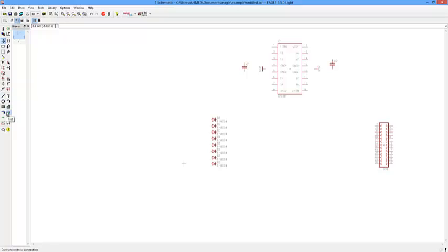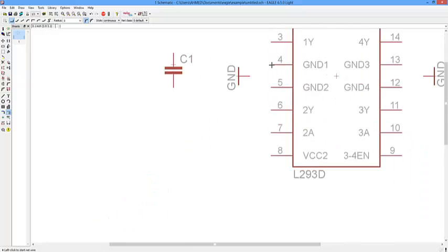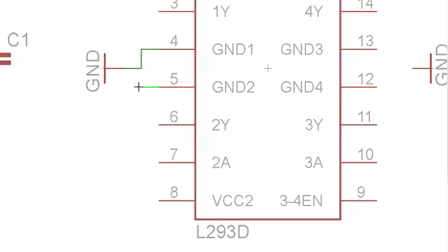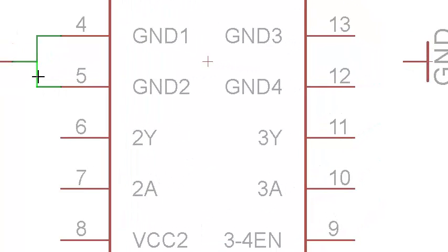Use net. Okay, so press on net and then go to the tip of where you want to connect. Press left click, then you get a wire. So just move the wire down and then terminate it at the ground. So each move of the mouse the wire increases, and when you press the left click at a location it will fix itself at that point, and then place it here.